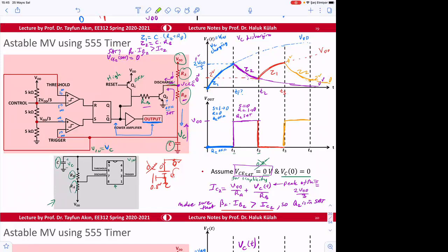Why? Because here the capacitor is charged and discharged, and there is a memory effect due to this SR latch, and that memory effect is making the trigger stages at two different points. So the same way that we did this, going up and then coming back was happening, right? On the way back, the voltage trigger point was different.